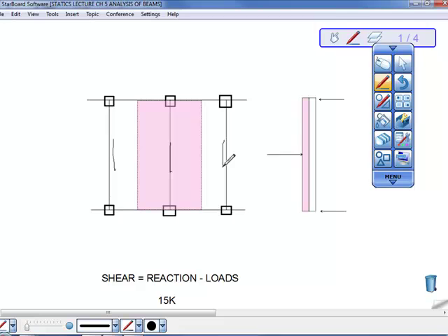Loads produce stresses in beams called moment and shear. So, do you know what a moment does? Tends to rotate. And what does shear do? Anybody know? The shear is more of a vertical force, which makes it want to slip past the other thing, or whatever's there. Moment is a rotation or a bending. So those are the most common stresses that you have to design against. Shear has a tendency to want to slice, like you said, and break it off. Moment causes the bending.